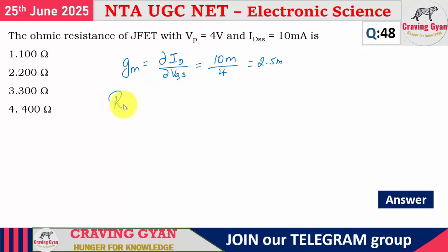Now what is the ohmic resistance rd, which is given by 1 divided by gm, which is equal to 1 divided by 2.5 milli. If I am sending it to the numerator, it will be kilo, 10 power 3, so 1000 divided by 2.5, you are going to get 400 ohms only. So for this, the corresponding option is option 4, which is correct.